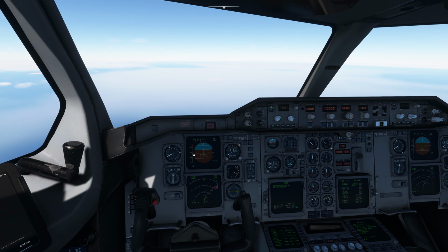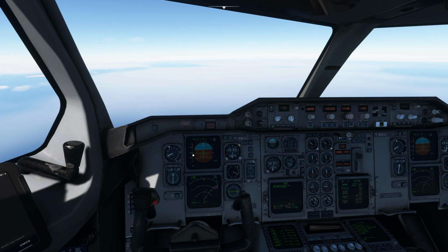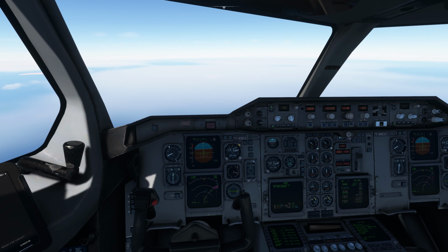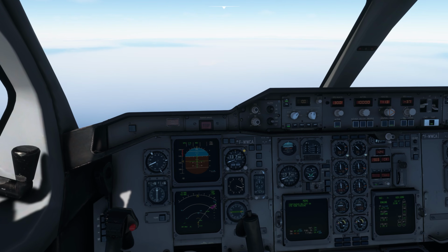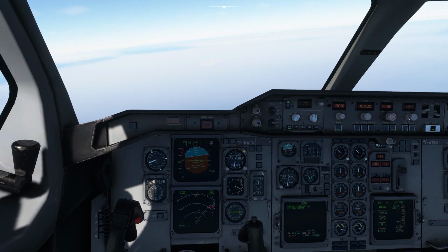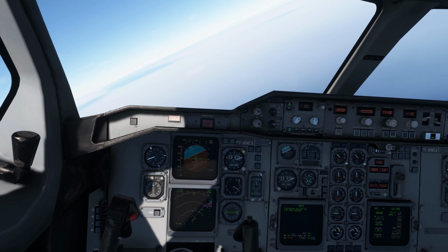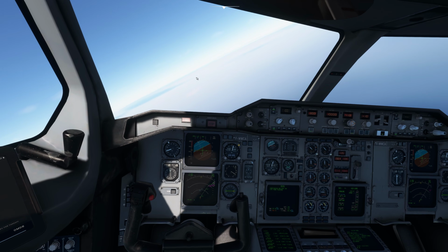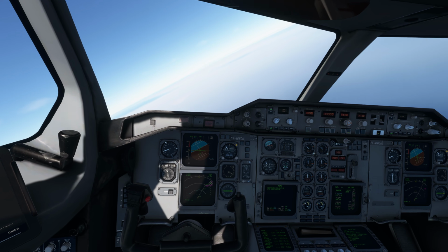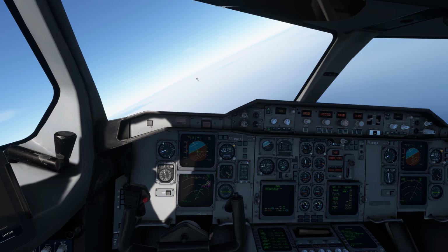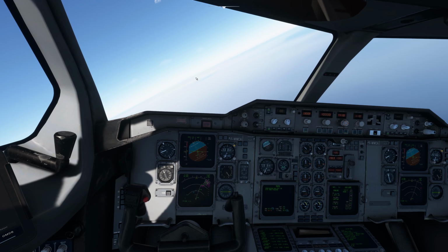6,000 feet, it's a very high rate of descent. You can now see the speed has started to increase. So that's why the vertical speed mode doesn't give priority to the speed, rather to the vertical speed. So this is just for the demo. So now I can keep it at 1,000 feet. This was just to show you the difference between the level change and the vertical speed. So during the descent, all you have to do is just manage the altitude and the speeds as per the given constraints, and that's it.